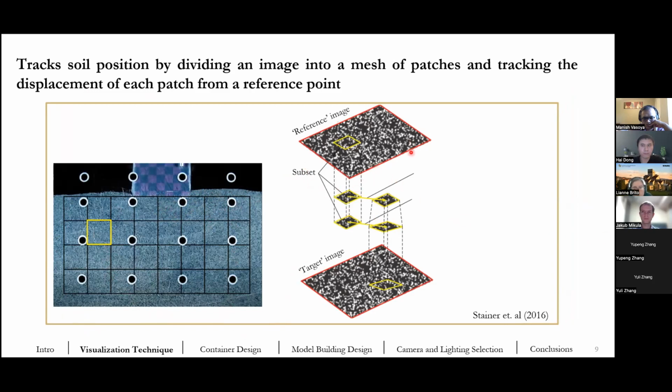This improved GeoPIV software uses normalized cross-correlation to obtain the integer pixel displacement, followed by a subset displacement to sub-pixel resolution. The current version of GeoPIV uses the reliability-guided method, and it allows each subset to deform using a shape function that describes a first-order deformation, in combination with other image intensity interpolation techniques.